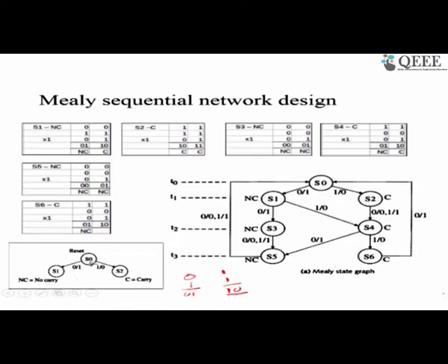On the other hand, in S0, when a 1 has occurred, we have to go to a state where the output is 0 and remember that there is a carry. So on 1 we output 0 and go to a state where we remember this carry.